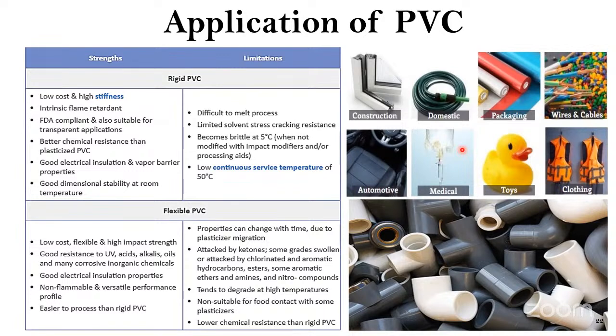So for PVC, whoever designs the injection molding, extruder, two roll mill or compression molding, they have very different specifications. I'm saying that. Otherwise, you can mold PVC in injection molding, extrusion, compression molding, and two roll mill also. But according to their property or application, the specification should vary. Is that clear?